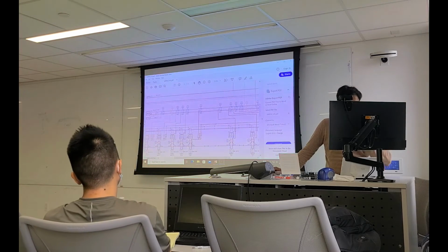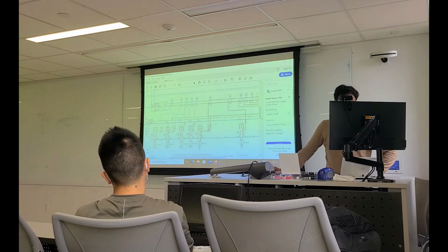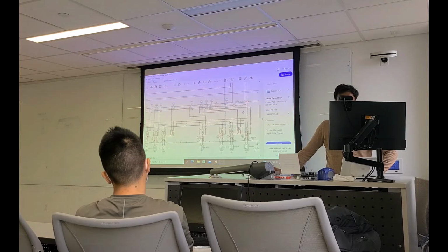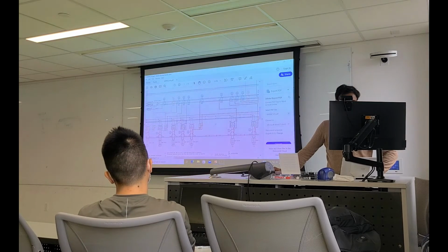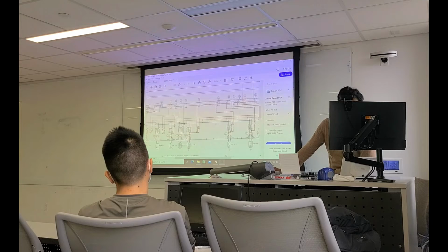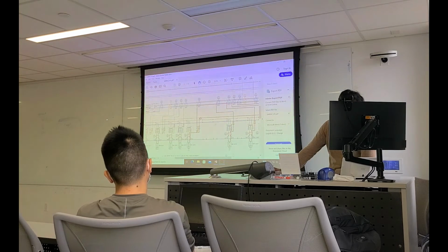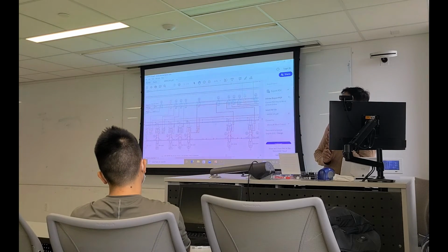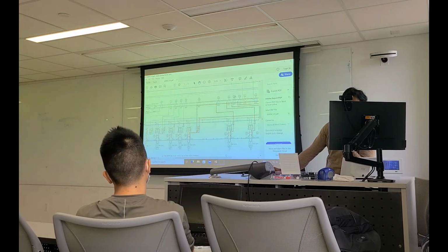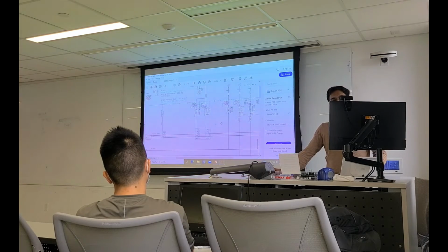So then it goes inside, it carries the source, and then I just want to show you the waistline. In some cases, you see your line is connected here, your EPC is connected here, so that is the waistline. Okay. So in dilution lines, your EPC is connected with the waistline. Then this is the dilution line, and it is connected with the waistline. Okay. But for others, there are two injection manifolds, one for group 3 precursors, one for group 5 precursors. Okay, so these are for group 3 precursors, and these are for group 5 precursors, and I will not talk more about it.